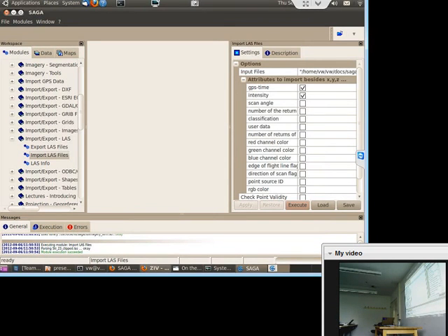Save as? This will save it as a SAGA point cloud. It's okay, so you can save it. But why? We already have it, no? Yes, but it's in RAM, and this would allow you to save it as a SAGA point cloud, so you can simply go to File, Load point cloud, and you don't need to import it from LAS.